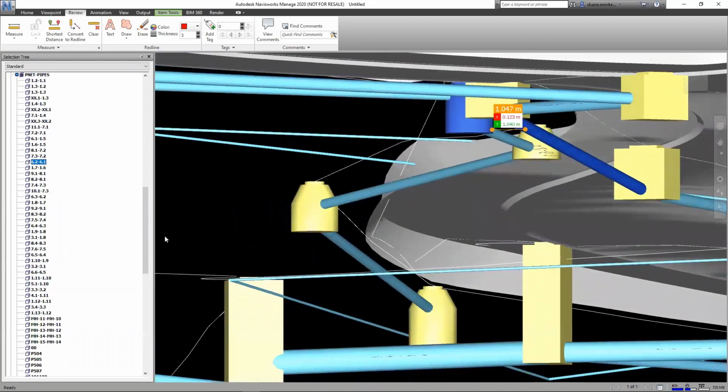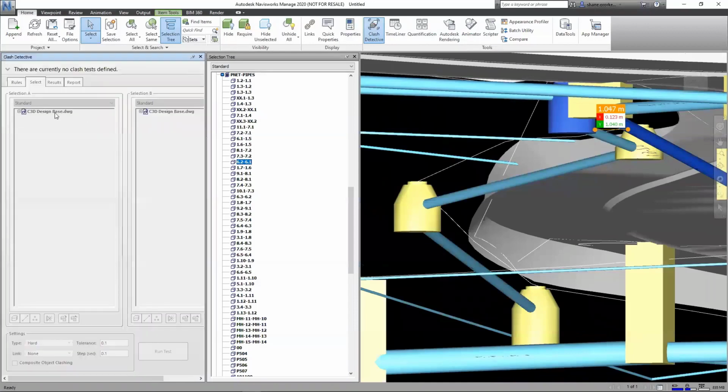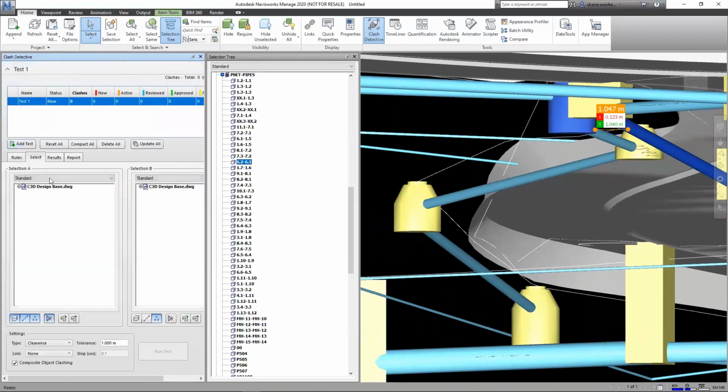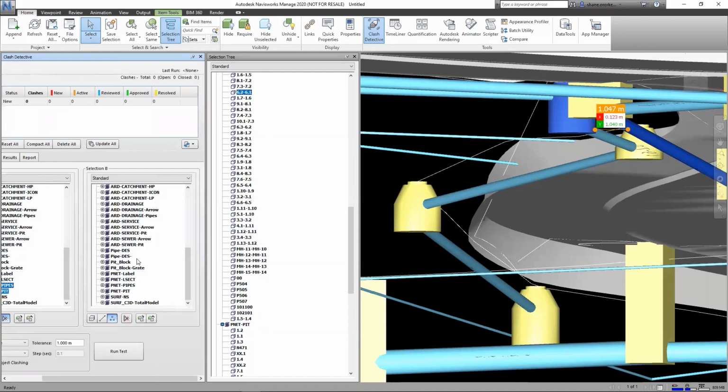If I want clash detection in Navisworks, then I should open up the Clash Detective. And then here you create a test, right? So I just need to add a new test. And what I'm going to do is compare the network of pipes and the network of pits. If I self-intersect them, I probably will get the lot, but I'll just compare it to other objects. The same thing, so twice.